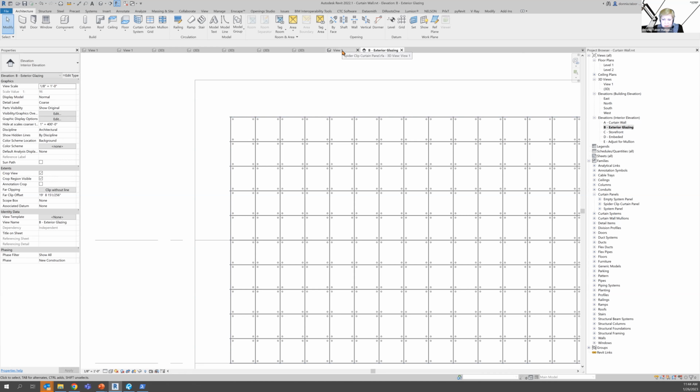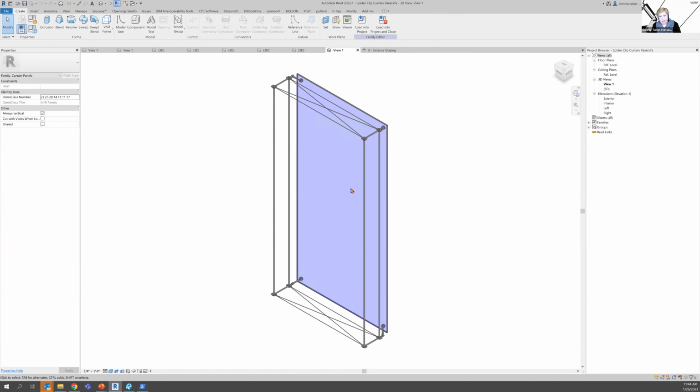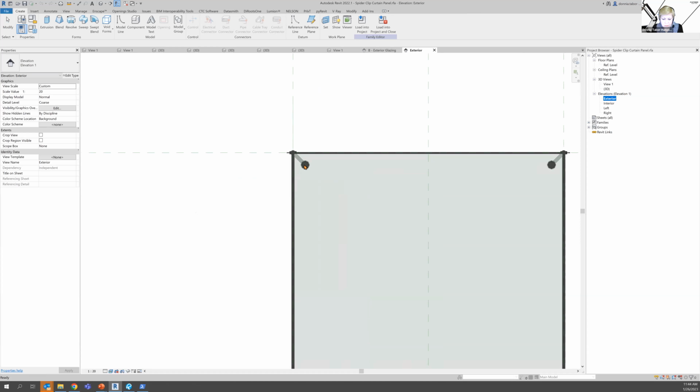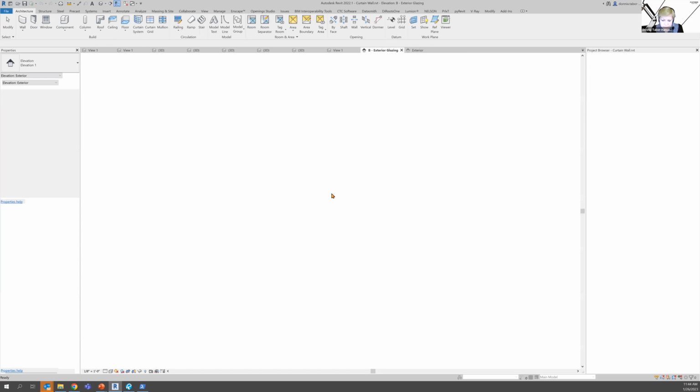But let's also take a look at that little rascal. This should be him here. Pardon me. The one thing about spider panels that you really ought to know is you only build 1/4 of the spider on each corner, so that when the corners meet together, the posts that would be here all line up on top of each other, giving you that spider effect that you see when you zoom in here.